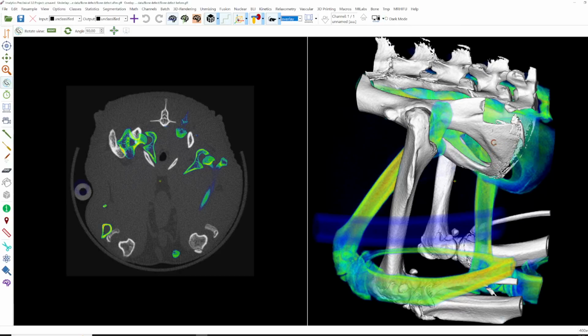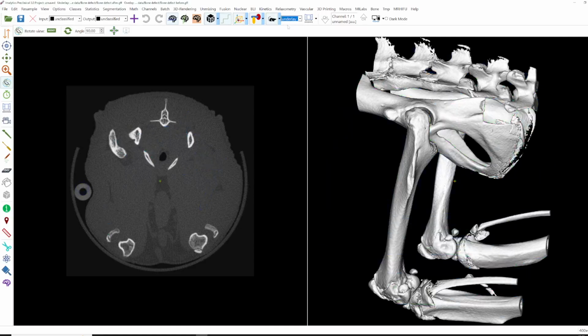I will perform some marker-based image fusion, and therefore I will hide the overlay. Focus on the underlay first. I will create some markers using the marker menu of the mouse action toolbar. You can find it on the left side here. I will use this hole, this small hole in the bone. Let me tick auto name markers, then it's faster. Here's also another hole. I will use it, as well as the arc here, and also here.